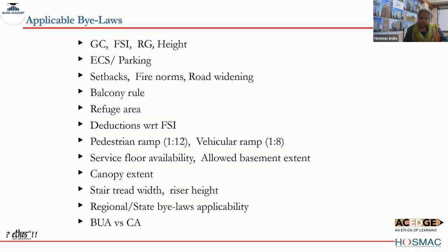So deductions with respect to FSI are calculated by the municipal architect, and in some buildings there are no deductions. Like in Kerala, I said there wouldn't be any deductions. Everything is in the built form. Pedestrian ramp is usually at 1:12, or vehicular ramp is allowed at 1:8, but better to build at 1:10. So these are some industry know-hows which I'm giving you, which will lead you to build a sound building, a hospital which should conform to these bylaws.